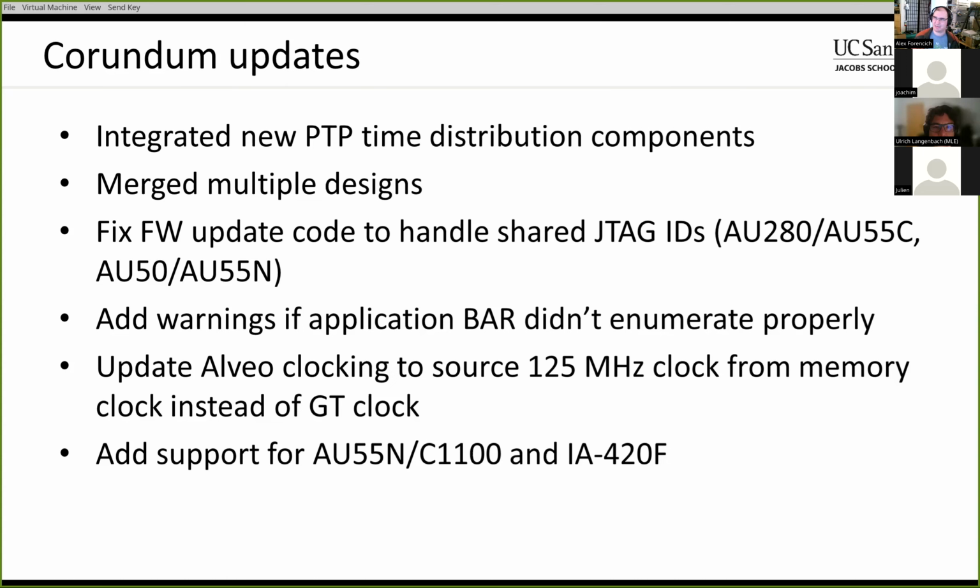And I did take a look at how Linux handles the bars, and I couldn't figure out if there was an obvious way to tell if a bar was present but hadn't been assigned memory. As far as I could tell, from the standpoint of the state in the PCIe device structures, it looks the same as if the bar is totally non-existent. So it's a little bit of a side note. There's a bit for unassigned, to indicate that a bar or a resource is not assigned. It seems like that should be set, but it isn't set.